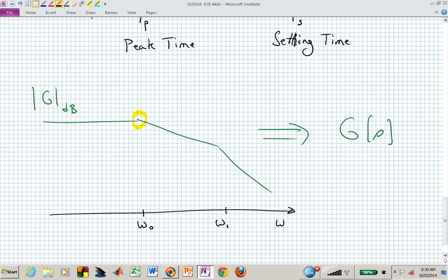I'm now in the S domain, the complex S plane, and if I am looking forward like you are, the left half plane is a good thing because there all the real parts of your poles have negative values, and that gives you this exponential decay that you need to have stability. Stability is based then on having your poles in the left half plane.